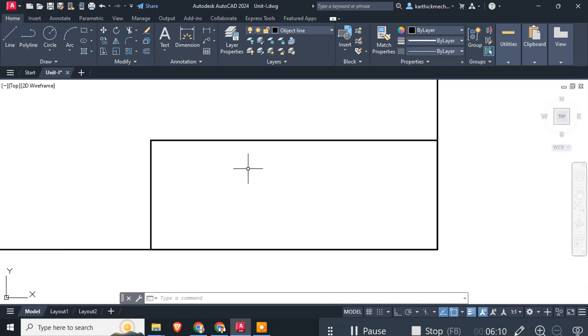Now we are going to separate this 60 mm. The height of the title block is 60 mm, and the length of the title block is 160 mm. So now this 60 mm should be divided into 6 equal parts. I have to draw this 160 mm line here at a distance of 10 mm from the y axis.